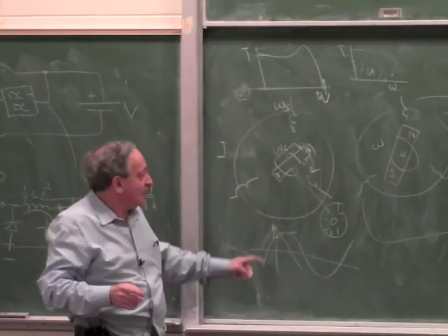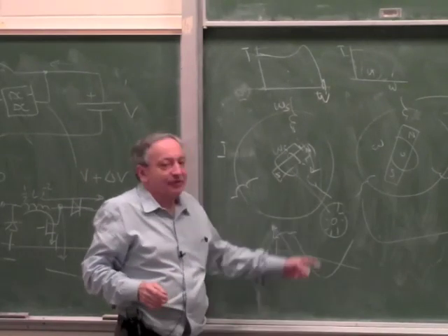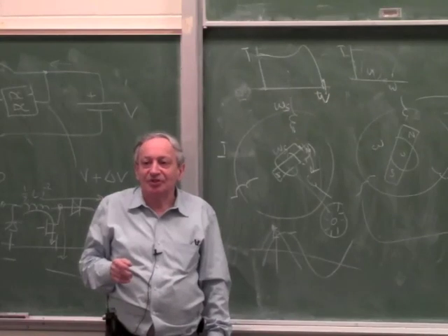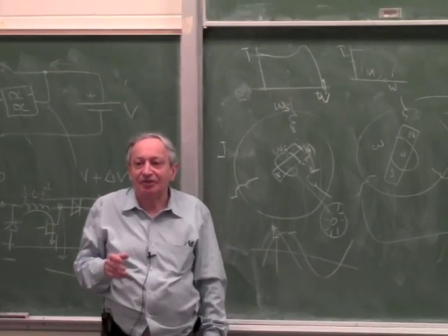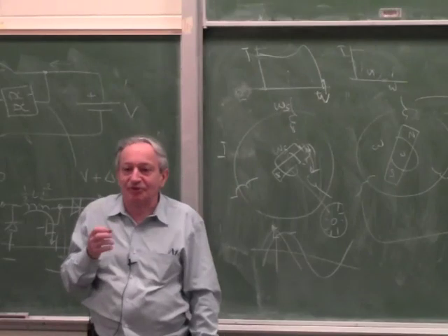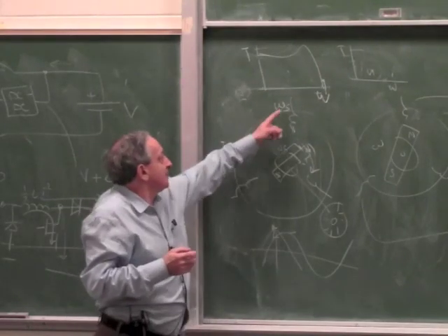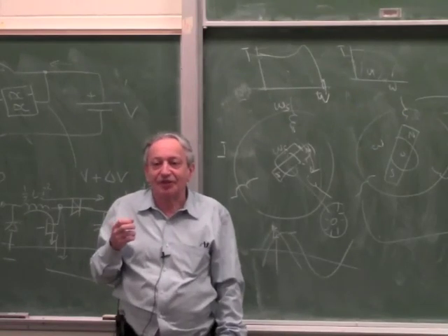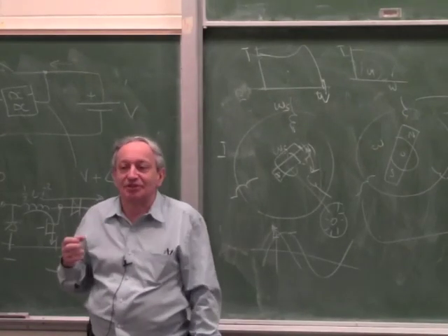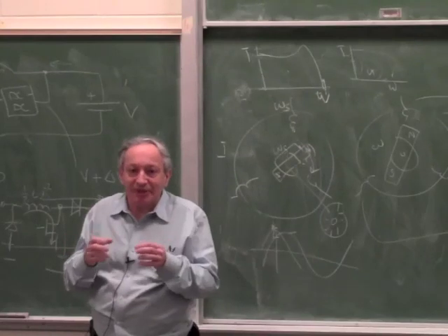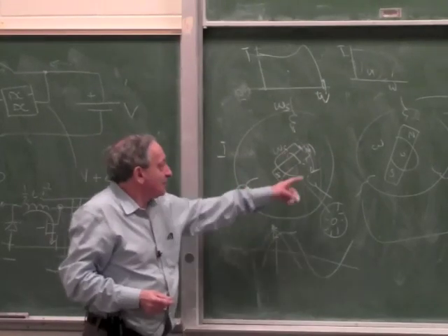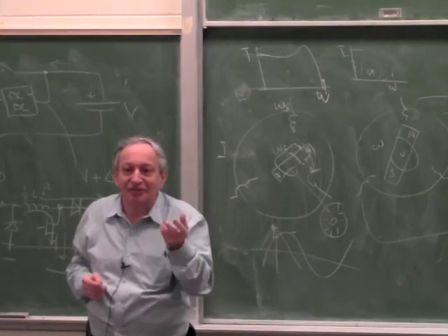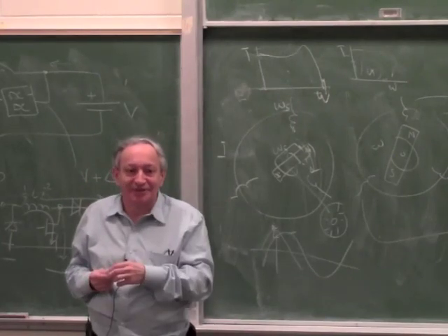So at any given moment, once you know the actual speed of the motor, what you do is you generate a rotating field which is slower than the motor, because you can control the phase and frequency of these three coils. So you generate a rotating field which is always, say, 10% slower than the motor. So at any speed down to 0, the armature is always ahead of the rotating field. And because it's ahead of the rotating field, the power flows backwards.